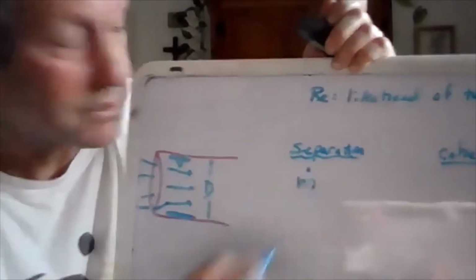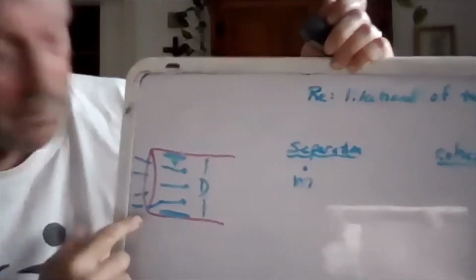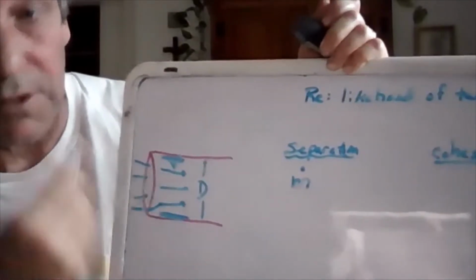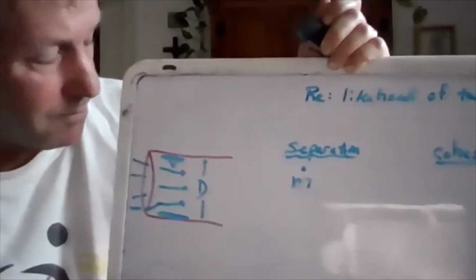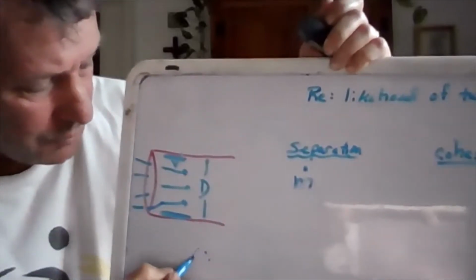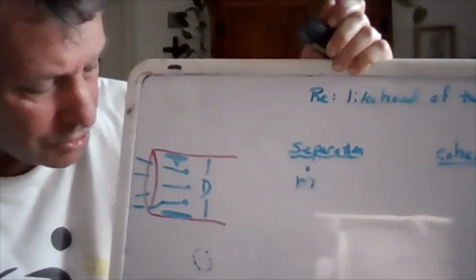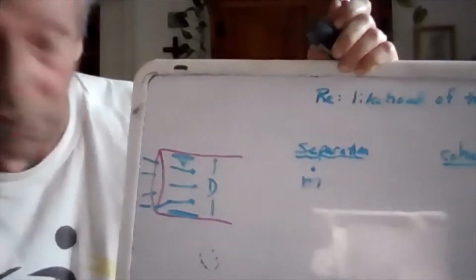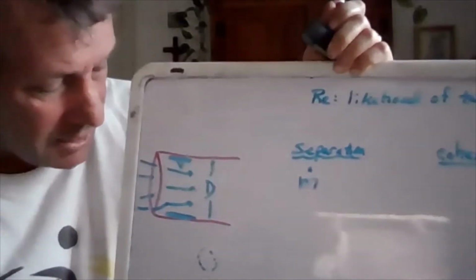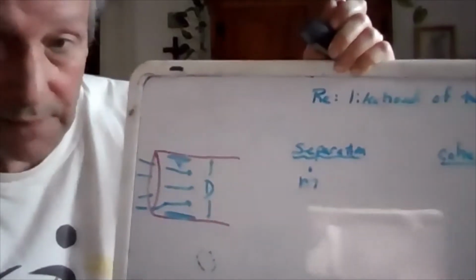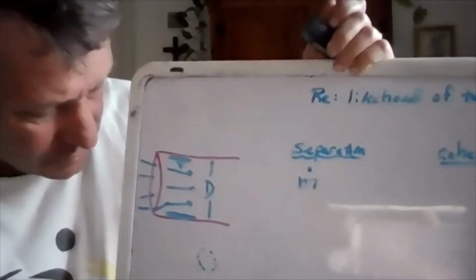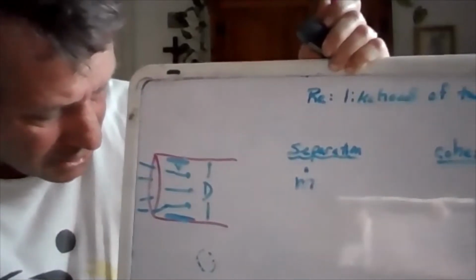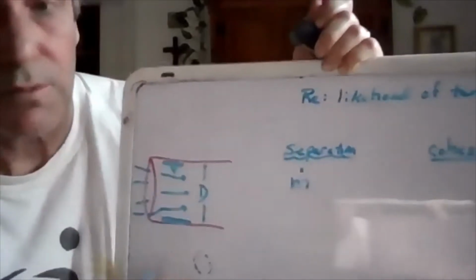That's going to make a difference. But what if we have a certain mass flow, like we're trying to put 40 pounds per minute through this pipe? What difference is it going to make as the diameter gets bigger and bigger? So we could imagine putting it through a small pipe or a larger pipe. Well, the larger the pipe is, the greater the area that fluid can fit through, and the less the effect due to the no slip condition that causes deviation around the edge.